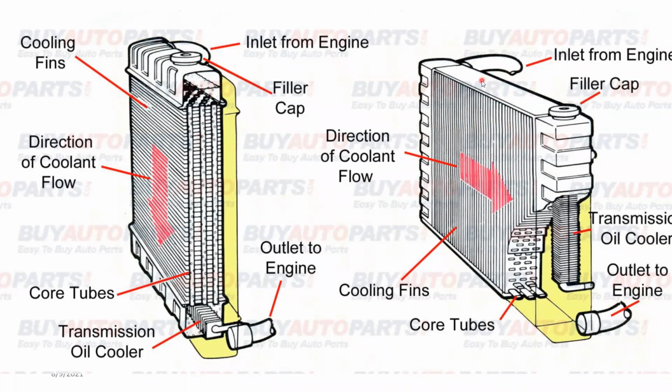Even with a bigger engine capacity, where more coolant capacity is needed, this arrangement may be most useful, because the radiator is going to be taller. The space between the hot tank and the cold tank is higher compared to this, so more cooling effect can be obtained.